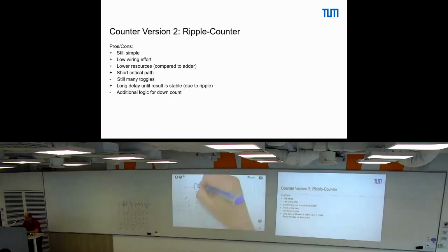Second event, we have this Q bar toggled to 0. So this is a 0. I toggle to 1. This internal state here, which is effectively what I write here, becomes a 1 because we have a rising edge here for that. Next rising edge, we have here 1. Q bar becomes 0. If Q bar becomes 0, we have a falling edge.